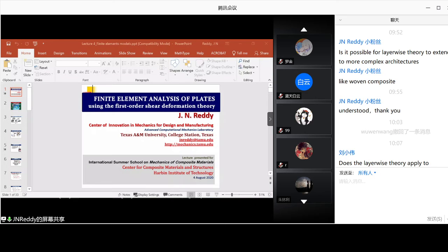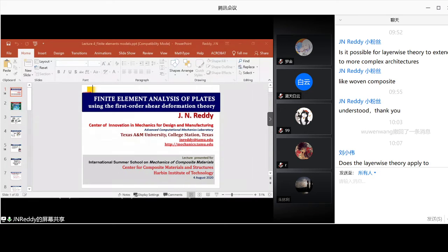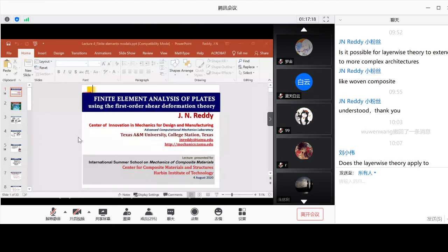Okay, so here, by the way, if you are not familiar, just please take it as something valid. This is what we call the principle of virtual displacements for a typical finite element of a plate. There I'm showing the stress resultants Nxx, Nyy, Nxy.